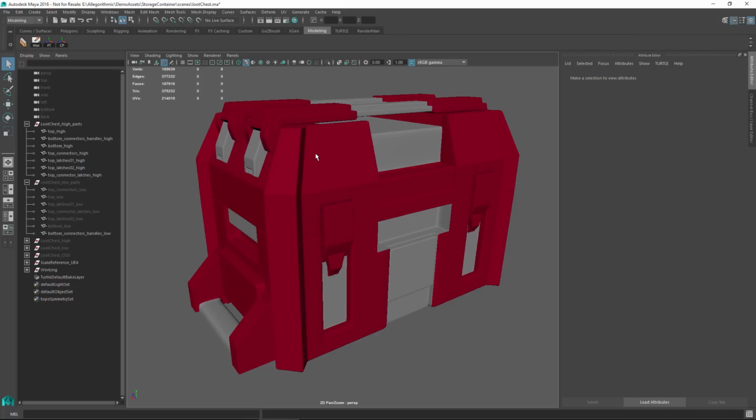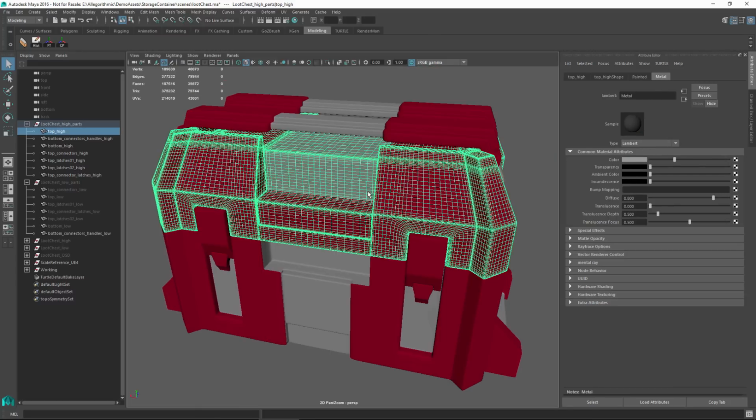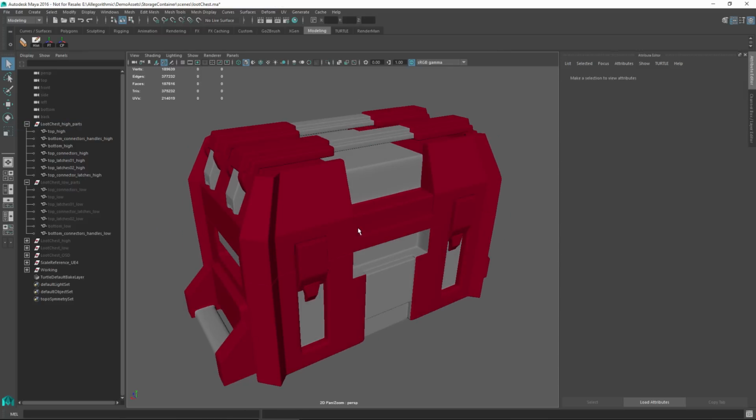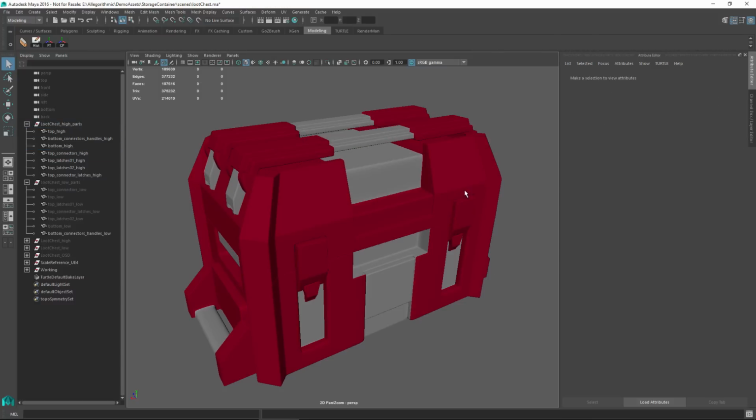So here I have my high resolution mesh. Notice here, I'm going to select this part. Notice this part has two different materials associated with it. This first material that I'm calling painted, I gave this a value of red. And in this second material, I just call this metal, I give this a value of gray. Now these material colors are going to be used for the IDs in the map. And it can be really useful because in your 3D program, you can design or rough out how you want the materials to be placed on your mesh just by assigning various materials to different polygon parts or faces, just to get an idea of how the material is going to look on your actual asset. So here we just save this high resolution mesh, and again, it's going to be used in that ID baking process.